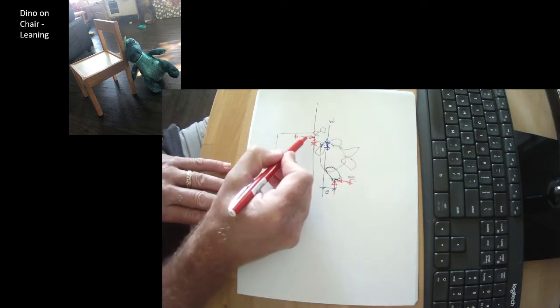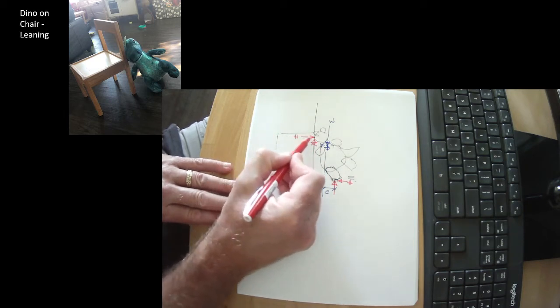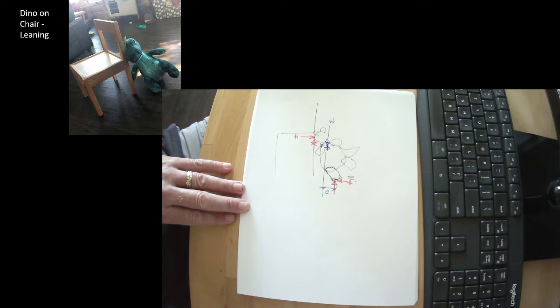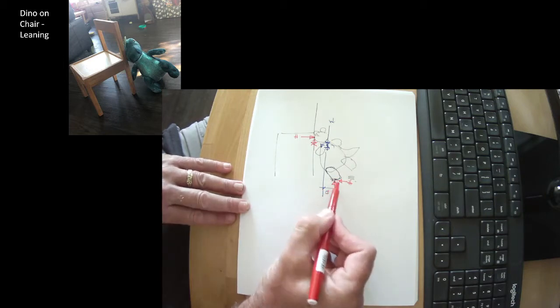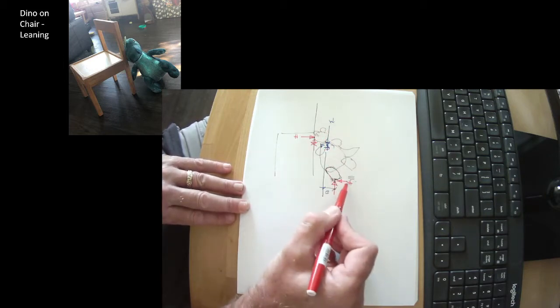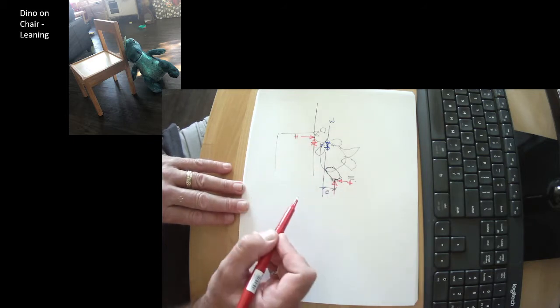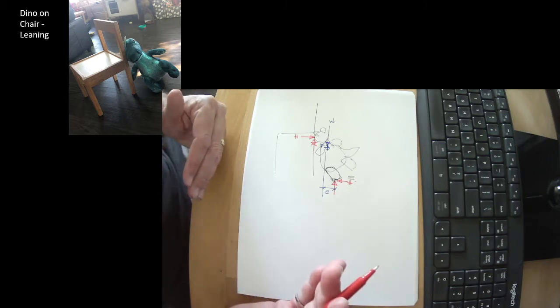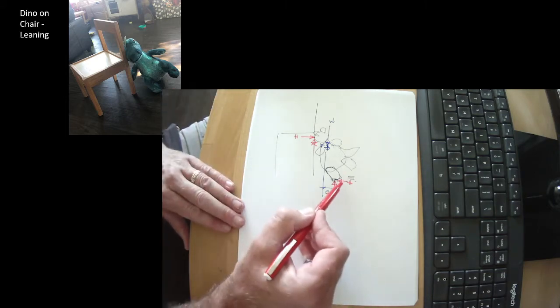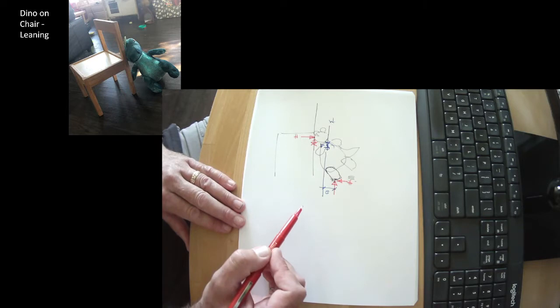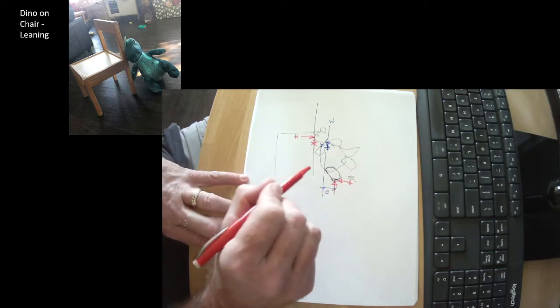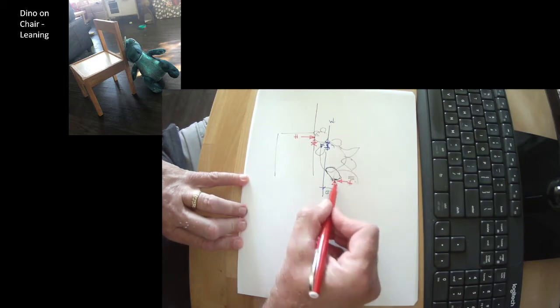We're going to assume that it's a frictionless surface, so it can only bear horizontally. And there's our free body diagram. Vertical reaction, eccentric from the weight, and the rotation is resolved as a horizontal couple between the feet and the head. Now, here is the challenge with this.